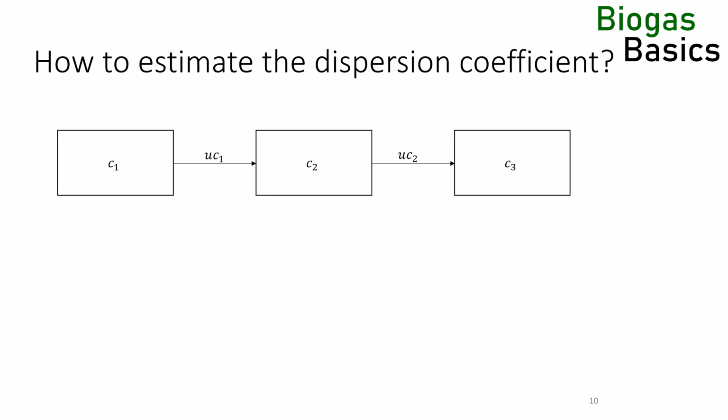Now we assume that superimposed on the directed flow, U, is another flow, V. Half of this flow flows upstream and the other half flows downstream. Because material cannot accumulate upstream or downstream, a flow of similar size must flow from upstream and downstream back into the section. The flows in both directions cancel each other out, but they move some of the reactant upstream and some of it faster downstream. The effect is similar to a random walk.